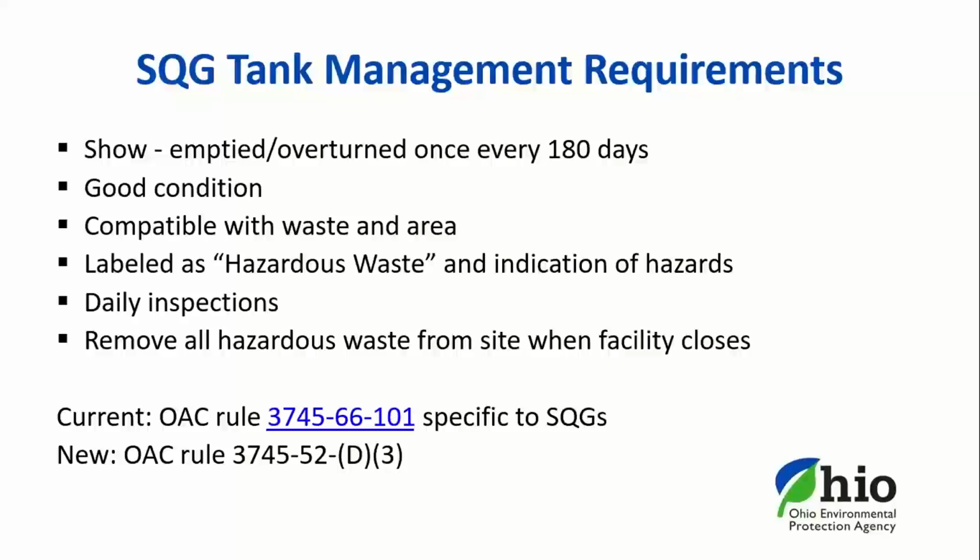For SQGs who manage hazardous waste in tanks, you can accumulate up to 999 kilograms of hazardous waste in tanks for up to 180 or 270 days without a permit, as long as you never accumulate more than 6,000 kilograms of hazardous waste on site at any time. You need to have a tracking system to ensure that the waste has not been accumulated in the tank for more than 180 or 270 days.